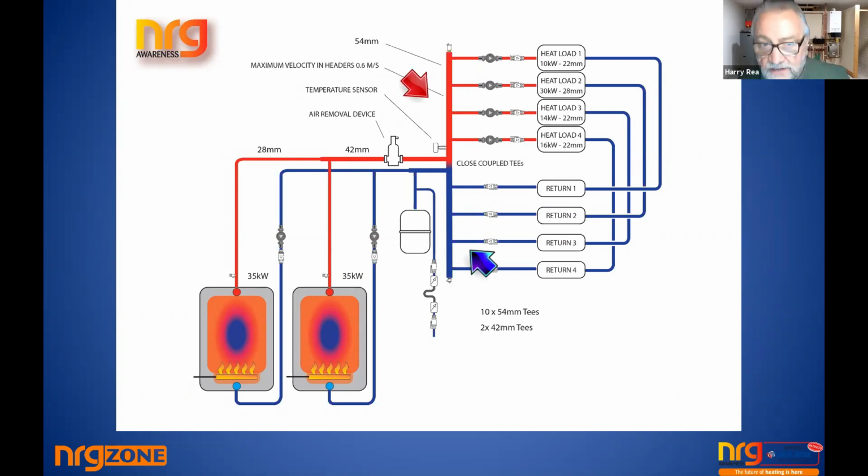And a lot of the time, it's because the common header isn't big enough. What actually happens, the water trying to get from this point to say this zone, when this pump is drawing, this pump has to pull against the vacuum that's been created by this pump and this one and this one. So therefore the last pump or the second last pump or the combination of the two of them, if the pipework is too small, is now going to be causing air to be drawn in on the vents, and it's going to be causing hassle with them circulating.